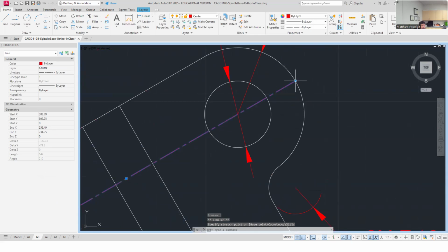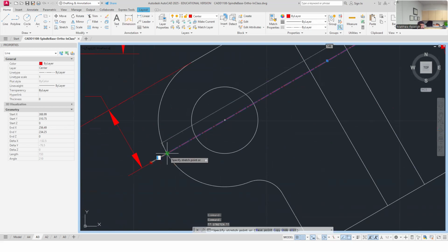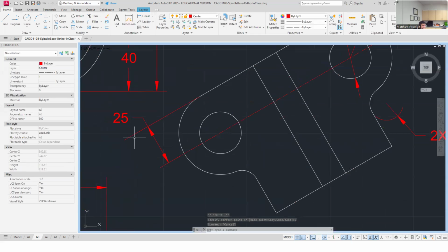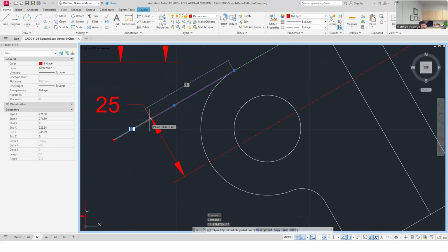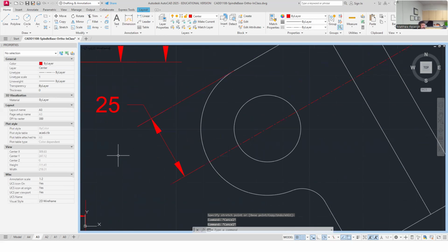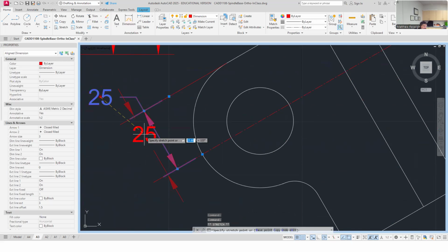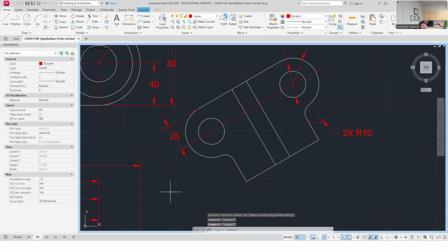I'm gonna follow the ASME standard here. I'm gonna pull this beyond that 6 millimeter. Here, I've got the same thing going on where I want to pull this 6 millimeter and let it overlap that extension line. I've got this locked in a little bit better there. I still am using this as what I'm actually snapping to perpendicular. So I'm going to pull this back to either the arrow or the end of where the extension line should end. I don't want that to overlap longer than the setting of the dimension style is. That's kind of particular, but maybe I'm going to drop this thing in between. And then eventually this is going to be spaced away. But yeah, I finally got it there.